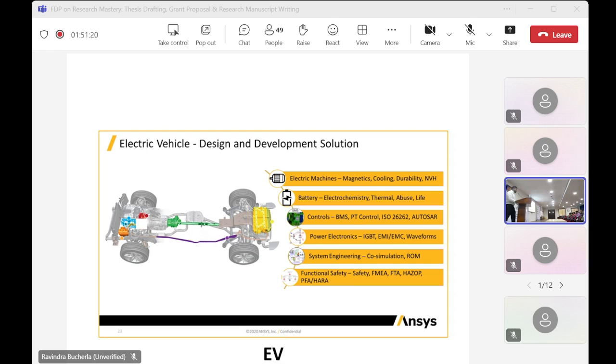Okay. So as we know that for every vehicle, we will be performing the crash test to get the safety rating. That is generally what we call it as NCAP, where we will be getting 5-star rating, 4-star rating. So we can simulate the complete vehicle when it is hitting any other vehicle, or when it is hitting a rigid wall, whether the person sitting inside the car is safe, or is there any damage at different areas, neck area, or head injuries, or side impact. So all this kind of simulations related to the vehicle engineering also we will perform.